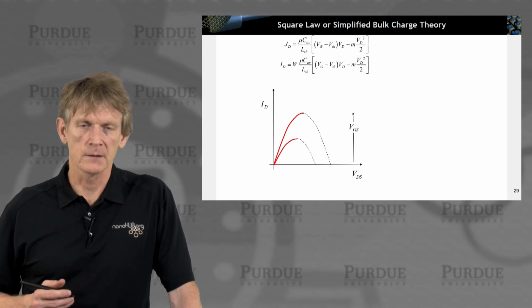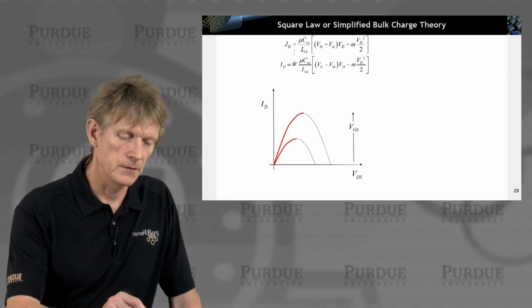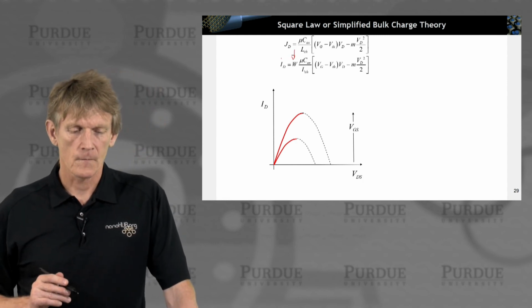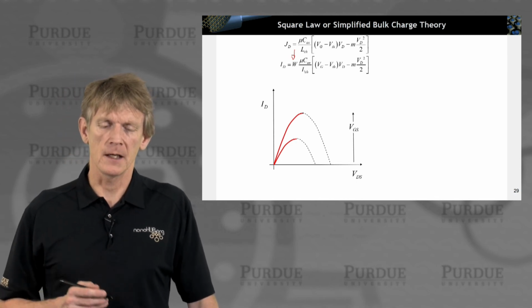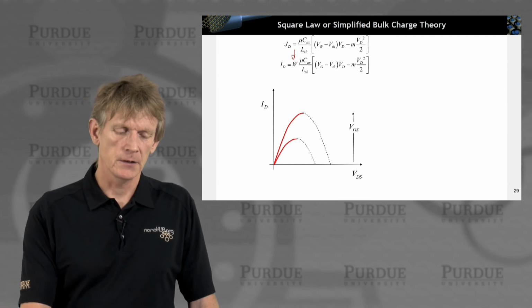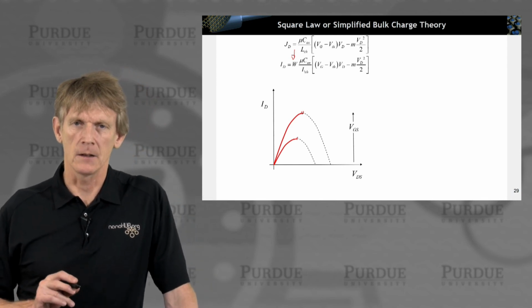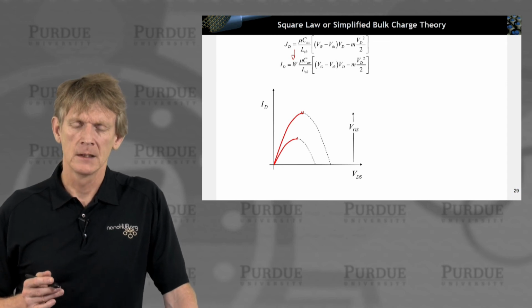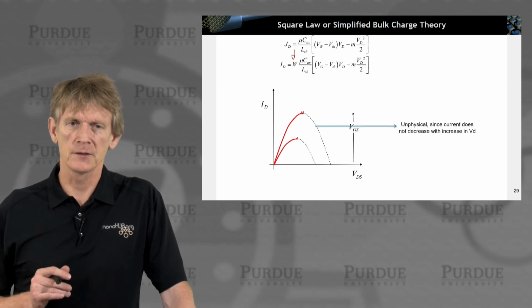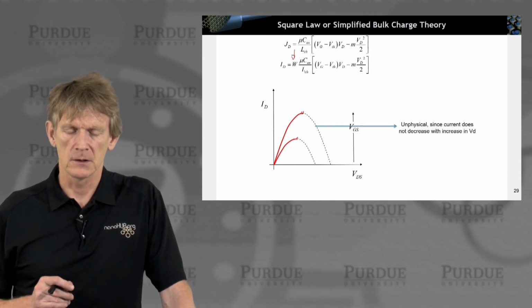Current density, we can multiply by the width of the transistors to get a current. So this is often done here. And you could plot this expression, okay? And it's a parabola, an upside down parabola. So it grows parabolic and it reaches a certain plateau, and then the parabola turns back down. Now, is this physically reasonable that the current turns back down? Not really. So these are unphysical branches of this expression,